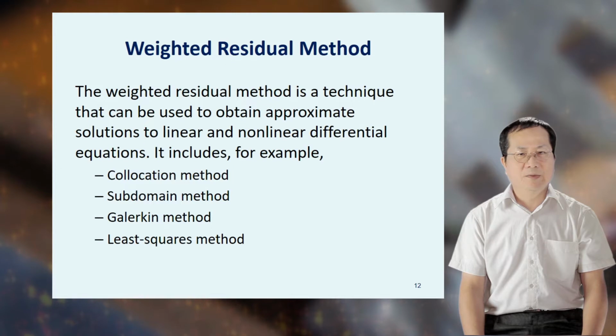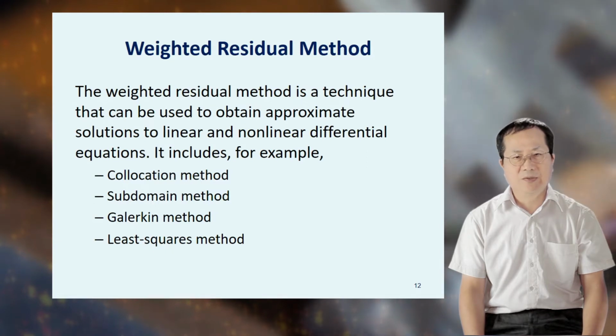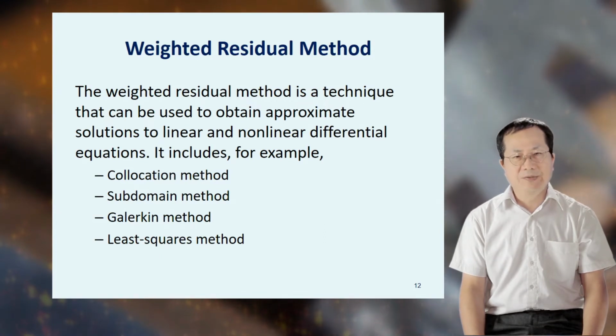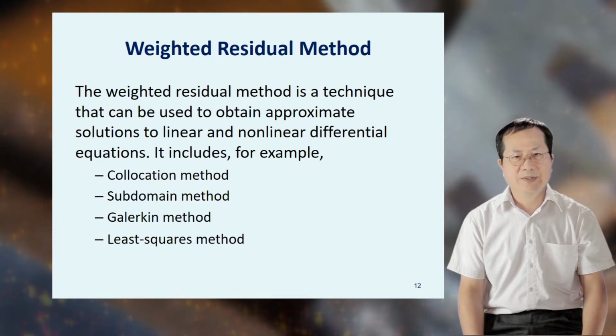In addition, the weighted residual method is a technique that can be used to obtain approximate solutions to linear and nonlinear differential equations. If we use this method, the finite element equation can be derived directly from the governing differential equations of the problem without any need of knowing the calculus of variations. This method includes, for example, the collocation method, subdomain method, Galerkin method, and the least squares method.